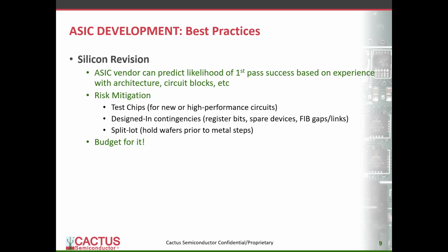And I already talked about holding wafers midway through the process so that you could use those wafers and maybe make poly up or metal up changes. Bottom line is you should budget for it, both in terms of schedule and cost, for a second revision.